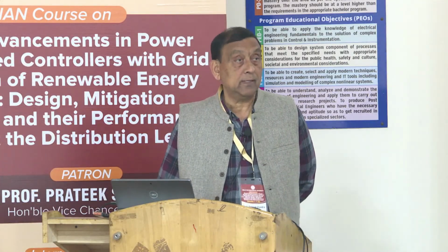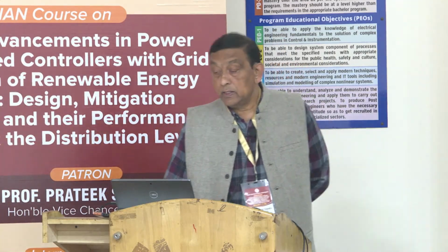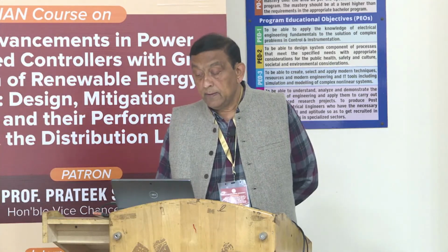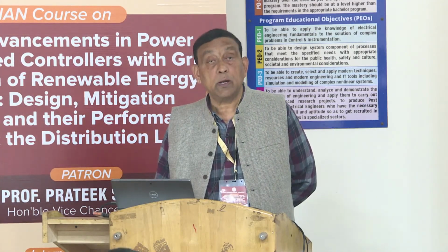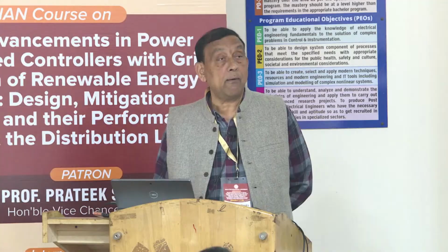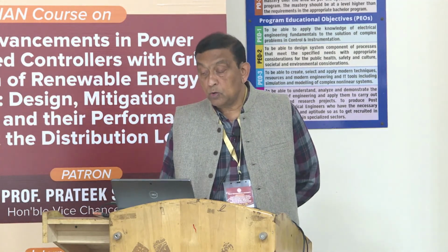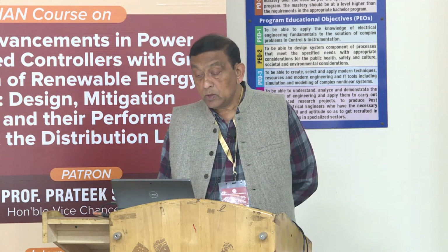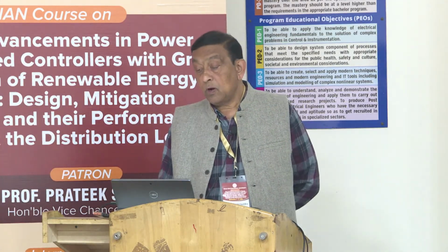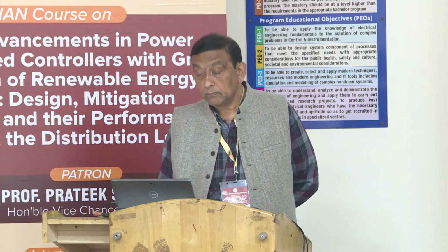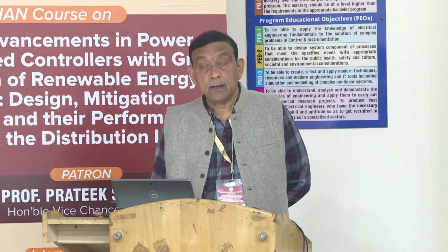Then short interruptions. This is what we were saying, that for a few cycles, if there is no electricity, it costs a lot of money, right? And it causes the following problems, impact on industrial products and those things. Then we were talking about undervoltage for more than 1 minute, which we may call brownout also. And then overvoltages. So everything we have discussed. Sustained interruptions for more than 1 minute, then we call them sustained interruptions, right? And then we were talking about voltage unbalance and how we are tackling this situation.